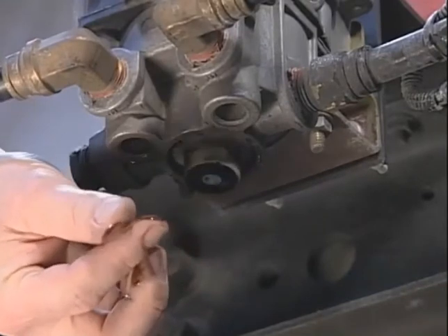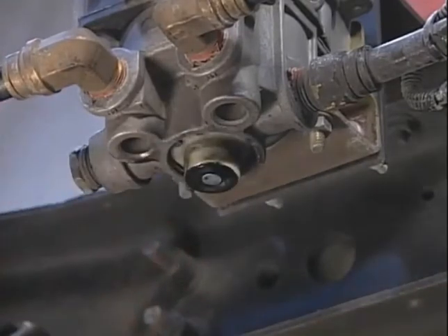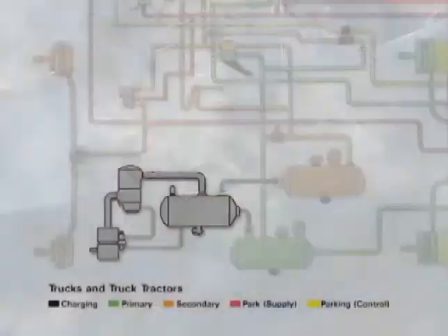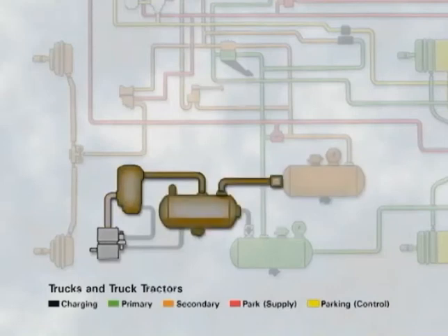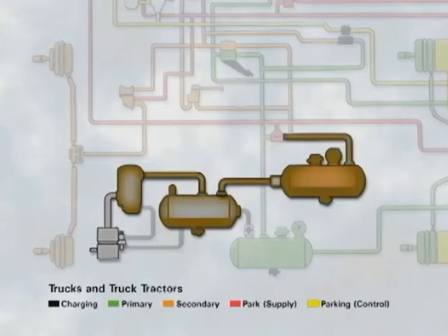There's one more visual indicator of possible air leakage: the presence of excessive oil on or dripping from the air valve exhaust ports. Some oil staining there is considered normal, since a functioning air compressor always passes a small amount of oil vapor, much of which is then removed by the air dryer. But excessive oil can mean troubles in the upstream portion of the air brake system. At the very least, it's a sign that system maintenance is overdue and needs to be done. Failure to do so can void the valve warranty.